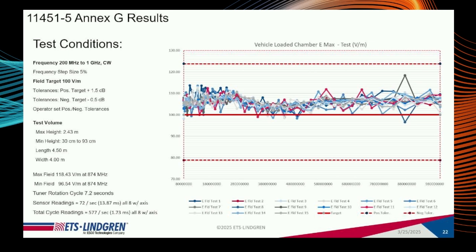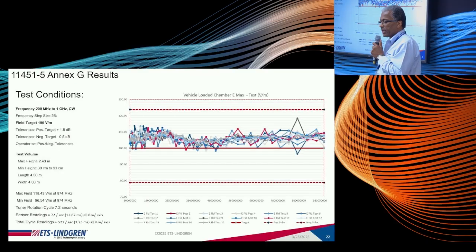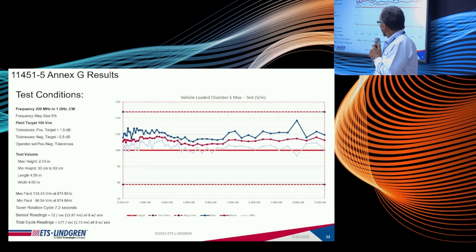is purely based on the fact that you have hundreds of samples that you're using during the course of that statistical analysis. Again, the advantage here is that you're able to take a high number of samples. We're measuring over 500 samples per second with those 8 field probes, doing the statistical analysis of the average field, and then leveling up to that target field level based on those 8 field probe readings.